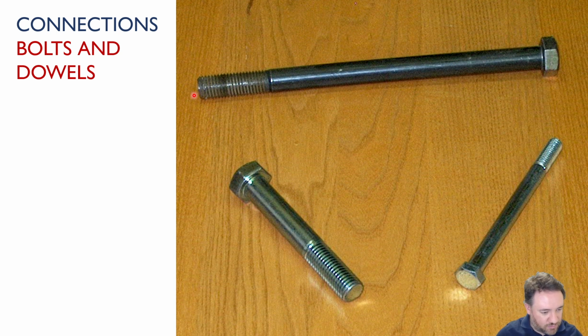So each bolt can transfer quite a bit more lateral strength than a single nail, right? You can get up to maybe 30 kilonewtons per bolt, something like that. But unlike nails, which I can just drive in and fit in between the fibers, for bolts we are going to have to cut a hole first. We can't just push a bolt through a piece of wood. It's too big, it can't fit between the fibers. So we're going to have to pre-drill for bolts.